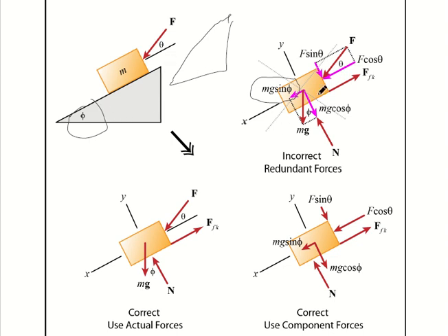We have two distinct angles. Of course, your F is going to go with the F cosine. Cosine is adjacent, and sine is the opposite. I see there's a little pink arrow showing you cosine means adjacent side, and sine is the opposite side of this angle. This is adjacent to the theta, this is opposite to the theta. You should be able to see it. And of course, you have F cosine theta and F sine theta in those directions. Okay, so now you can see that all of the coordinate axes are drawn in the free body diagram.